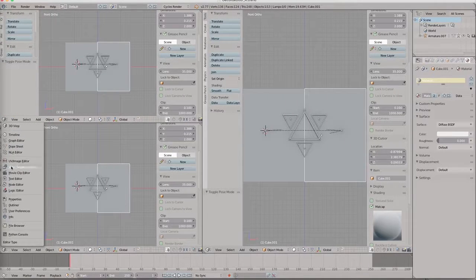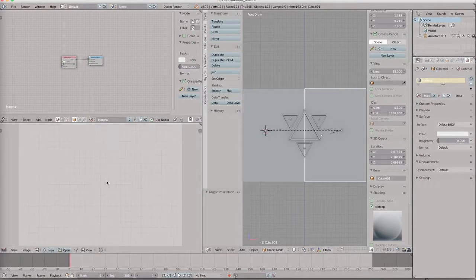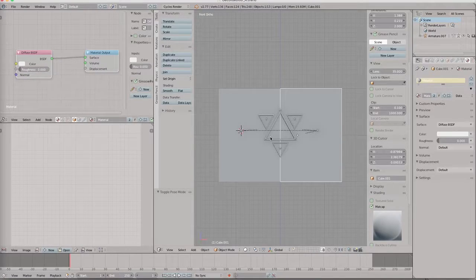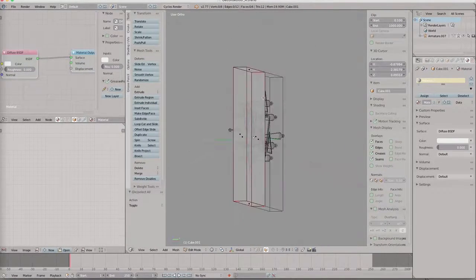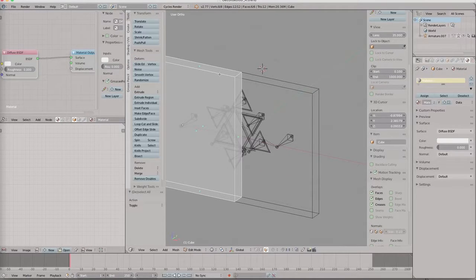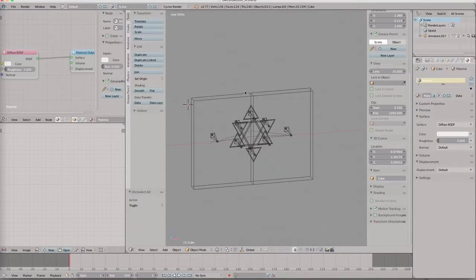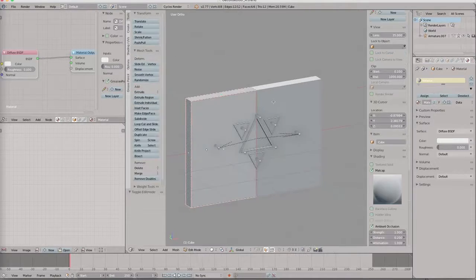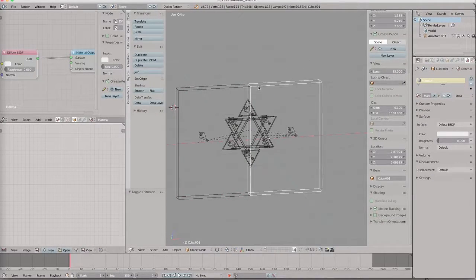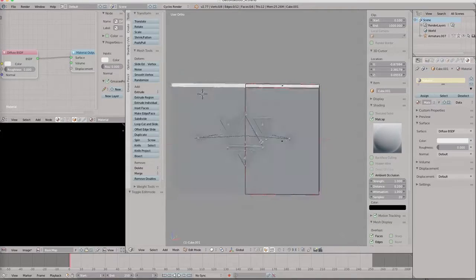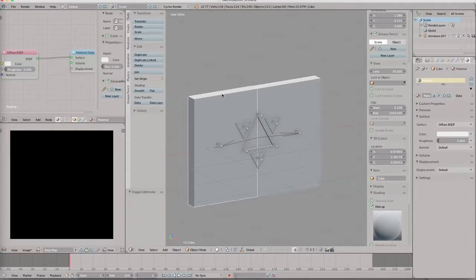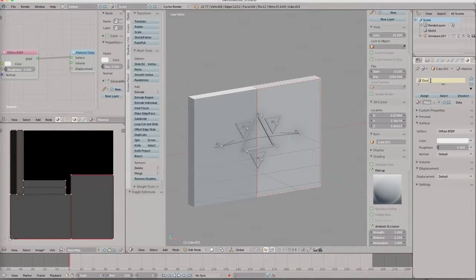As I said before, even though I'm not really going to use a UV map, I might later. I might talk to other people, the programmers or other game designers, and they might say, well, we want to add some different textures. We don't necessarily want it vertex painted. So make sure you take the time to unwrap all your objects, all your components, so that it has more options. That's my advice.